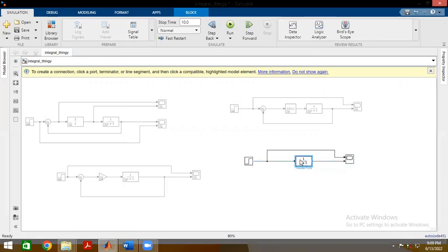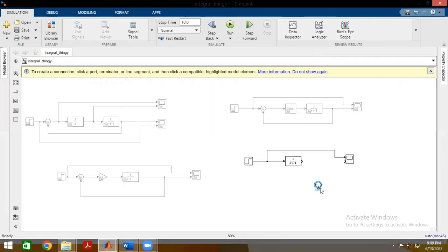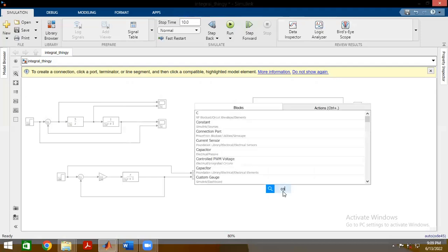We're already getting that. What if we have a disturbance? And a disturbance in the context of a buck converter could be the load changing, or the parasitic parameters changing in the design of the buck converter. Remember, we designed our buck converter to operate for a 2.5 ohm load.